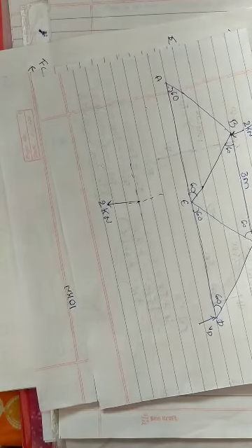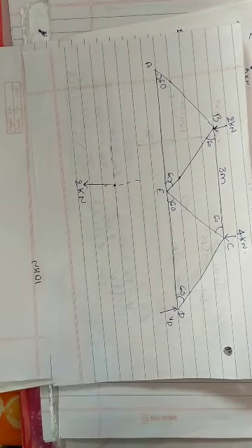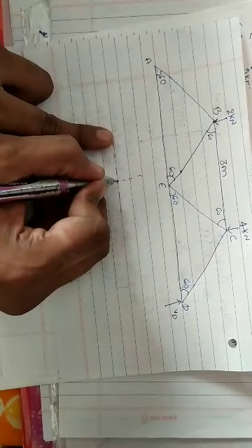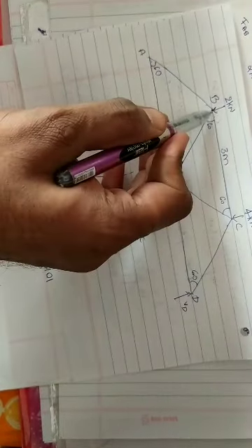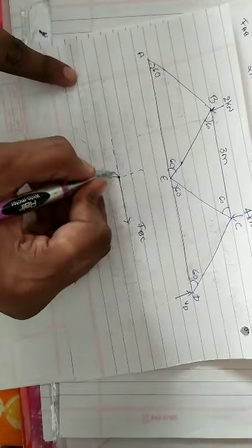Now what I said, when you consider a joint, we have to assume that each force is a tension force. Tension force means acting away from the joint. Now this is FBC, right? Now FAB, a tension force, is acting away from the joint, so it is acting in the third quadrant.